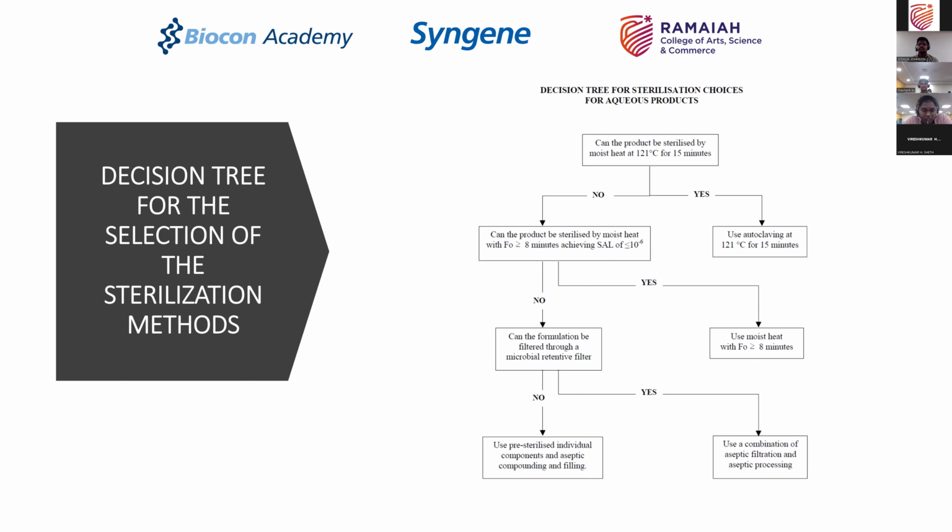Same thing you do from tank 2 to tank 3, where two different systems or two different solutions are prepared, and they are filtered and then filled into tank 3, where suspension gets formed. And there you may have added an API in tank 2, or you will directly add into tank 3. When you add that, you are able to filter, sterilize it, because those solutions are filterable. They can be filtered without a problem, because you are still not in a suspension situation.